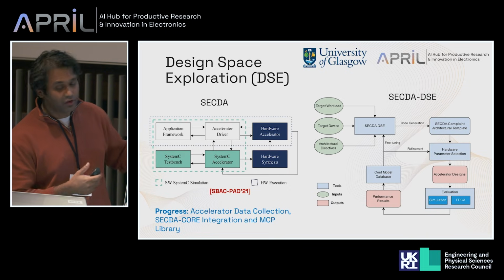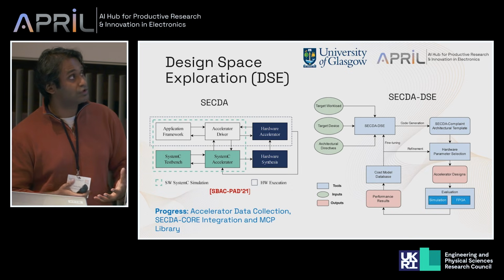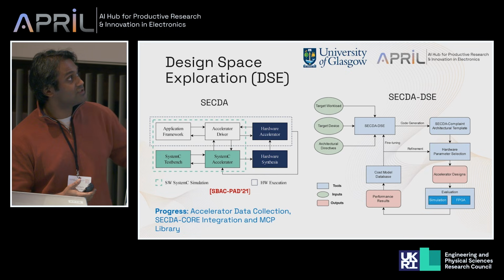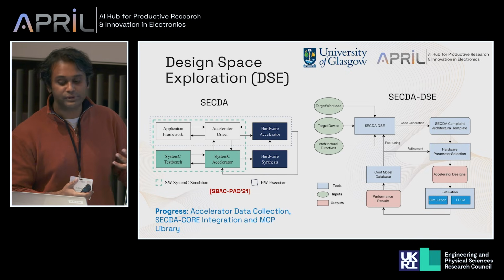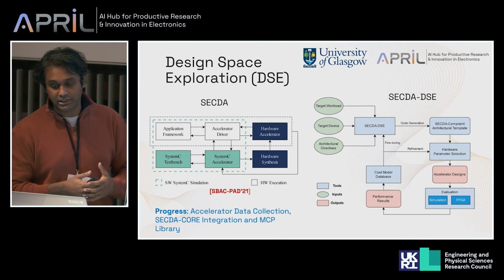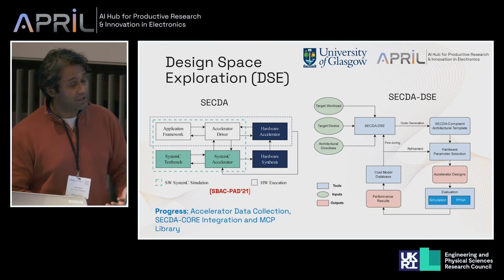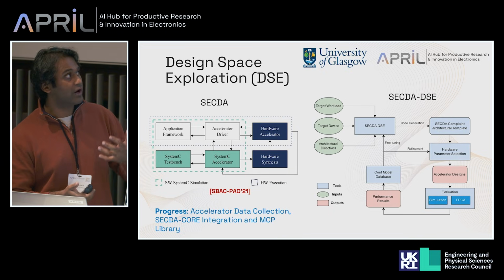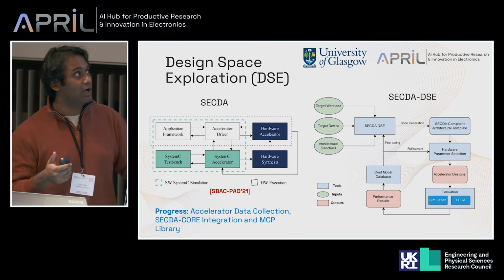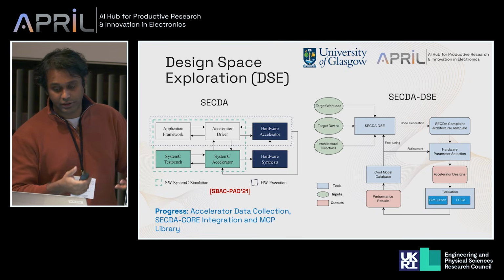So with that design philosophy explained, SECDA-DSE looks to improve upon it, because the first design philosophy requires an expert user to understand many different components and make changes to the design. SECDA-DSE basically takes the target workload, so whatever AI models you have, the target device, so your AMD FPGAs, your Intel FPGAs, and some architectural directives, so what kind of data flow your architecture wants, is there a micro ISA, is there a systolic array, or the architecture of the accelerator that you want.